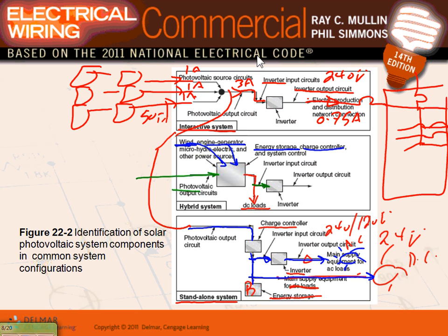into an inverter. I can invert it back into an inverter output circuit and feed all my loads at AC level. And the smaller inverter, 3,000 watts, does the same thing. 3,000 watts? Yeah, you have to buy an inverter that matches your load. Yeah, you can have 5,000, 3,000. This inverter? Yes. You're taking from the inverter power at the AC to feed the load.